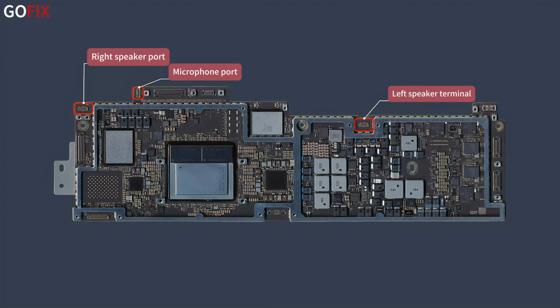We'll use the first USB-C port as an example. F400 model CD3217 is a PD controller customized by TI for Apple. It handles transmission, identification, and negotiation of the USB PD protocol. This chip has a built-in bidirectional power switch. Whether it's charging the machine or providing external power, it must be switched and managed through this chip. Therefore, it's a core chip that requires significant focus during the repair process.